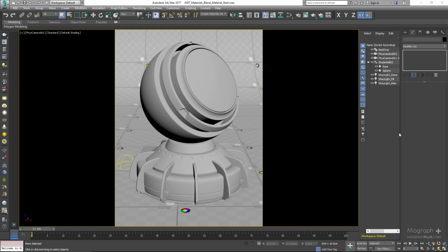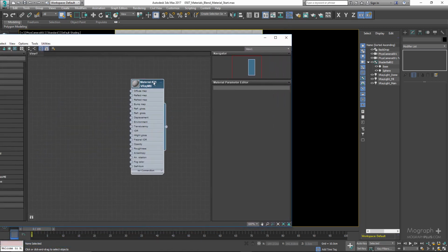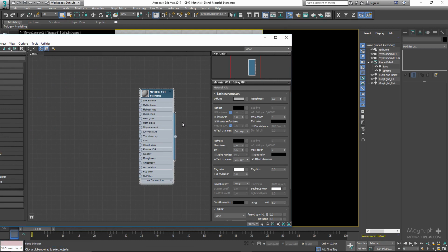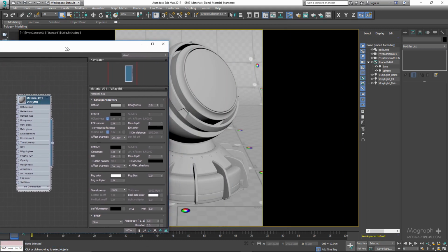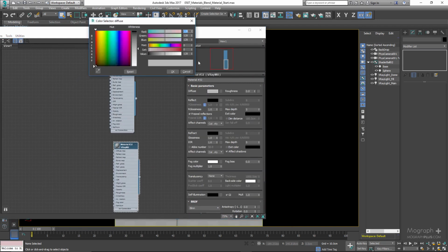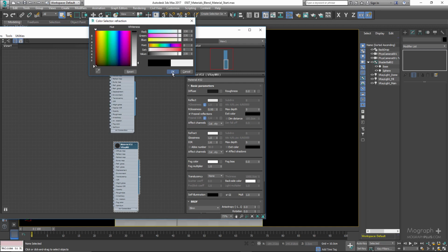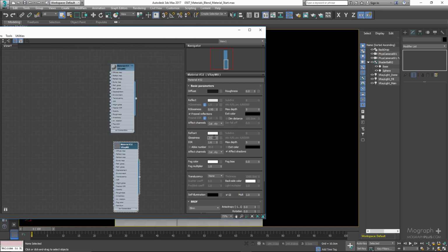Let's open up our material editor. Right now I have this simple V-Ray material applied to my shader ball object. Let me just copy this material and create a glass material. So dark diffuse color, reflection to something like 200. We can set reflection glossiness to 0.95. Refraction color can be 230. And refraction glossiness maybe to something like 0.95 as our reflection glossiness. And IOR of 1.5 would be enough.